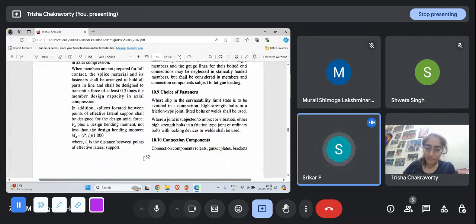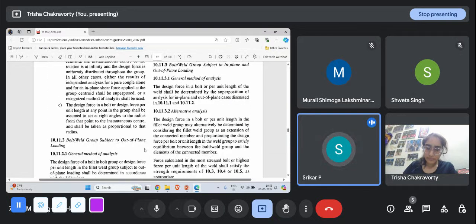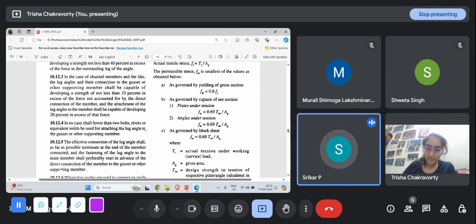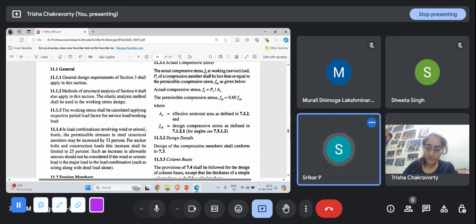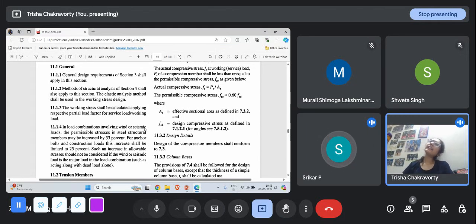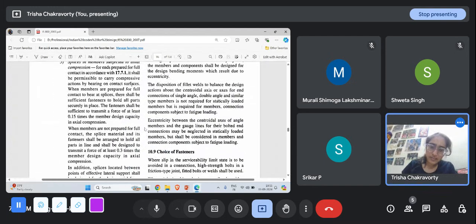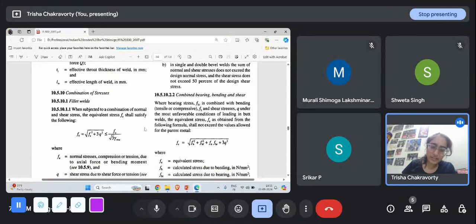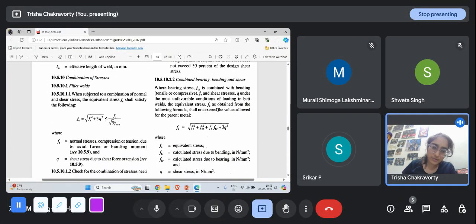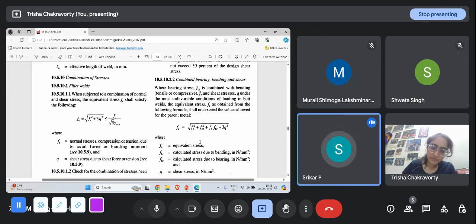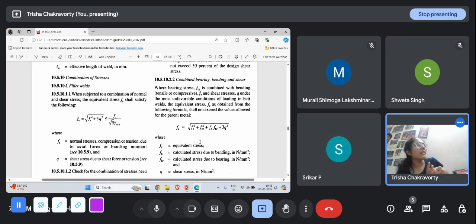These two things are a little different when we consider whether the load is perpendicular to the plane of the joint or parallel. I think in eccentric loads we always use the resultant, right? Have you ever seen this formula being used for an eccentric connection? Ma'am, while considering eccentric loading where it is perpendicular to the plane of the joint, we will get tension and shear. Yes, right, right.